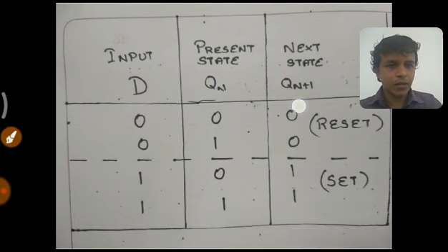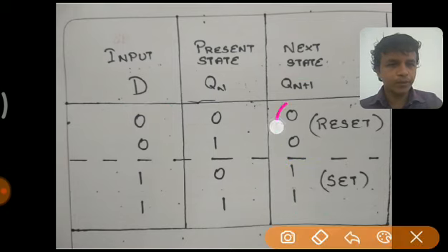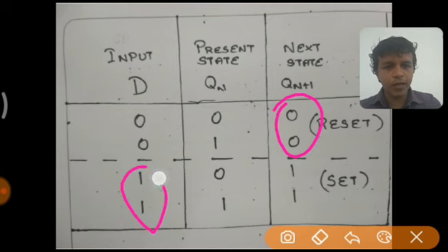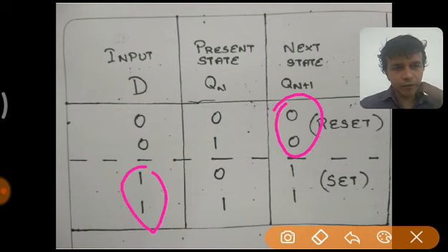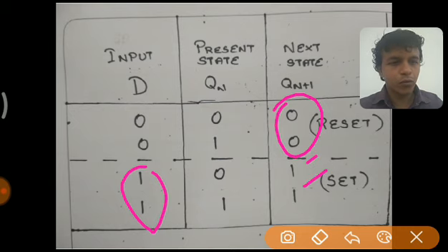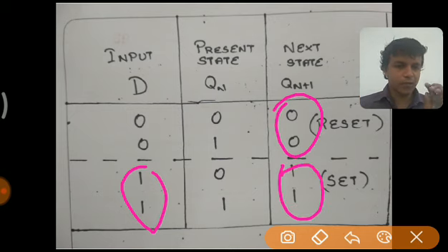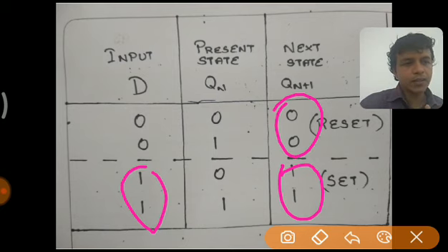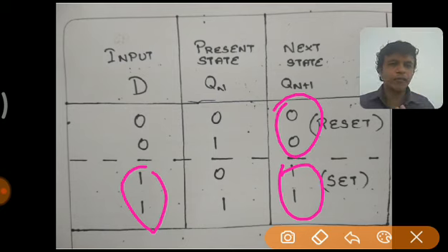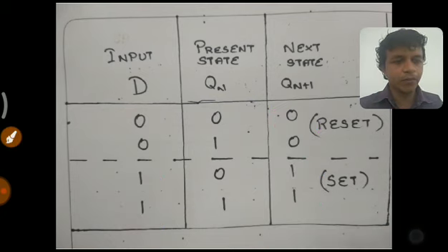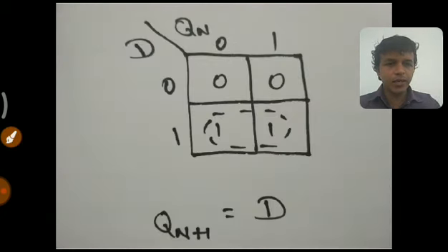Similarly, now 0 is available on the flip-flop, but we are giving an input as 1 to the D flip-flop, so immediately it does not change its value to 1. It waits for the clock pulse. When the clock pulse is activated, it makes its value 1. So a delayed value is present. Whatever input we give, it appears at the output, but at a delayed time period. So that is why we call D flip-flop the delay flip-flop. So this is regarding delay flip-flop.